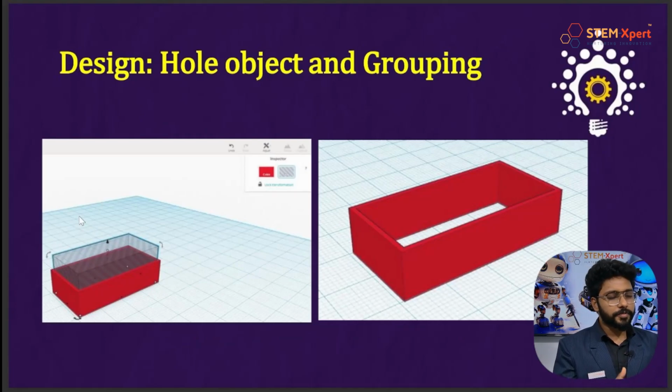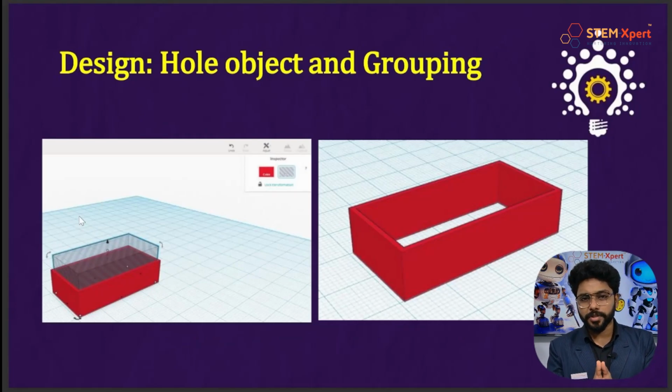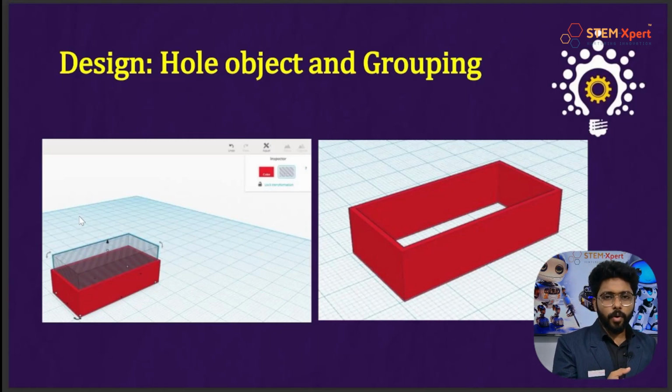So there are certain steps that we need to follow here. At first we are adding a box into the work plane, and we will change the dimensions accordingly. This box is used for making the wall design of our home. Here we will be making the wall design of our home. There we need to cut down a portion from the old object.